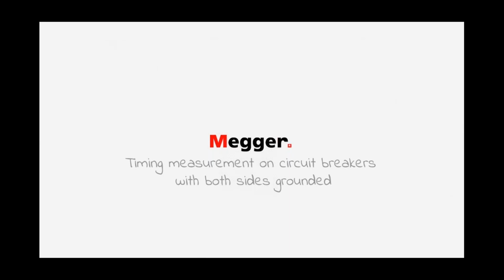Because of the lack of maintenance, they tend to have that lubricant getting dry and sticky, and worst of all, if a bad type of lubricant is used, that can lead to losing the lubricant properties even faster. So you need to always check with the circuit breaker manufacturer what you need to lubricate and what you don't need to lubricate, and what lubricant to use.